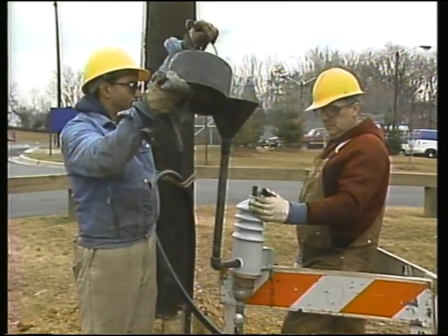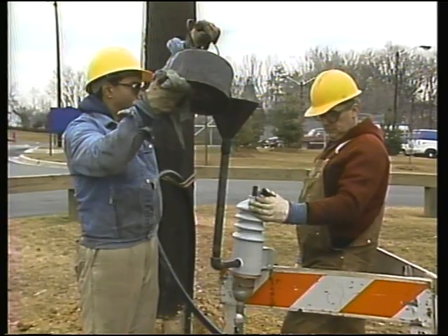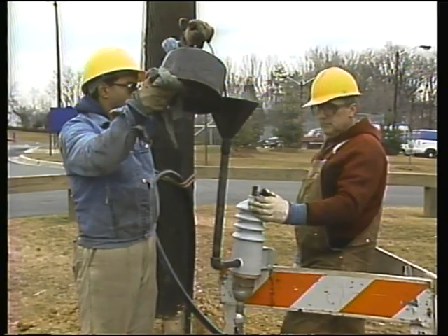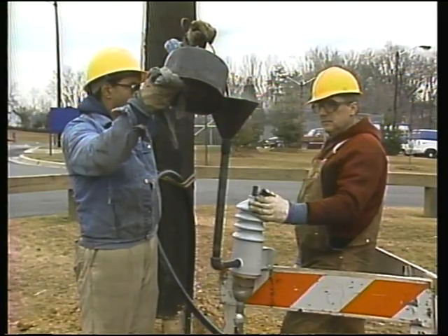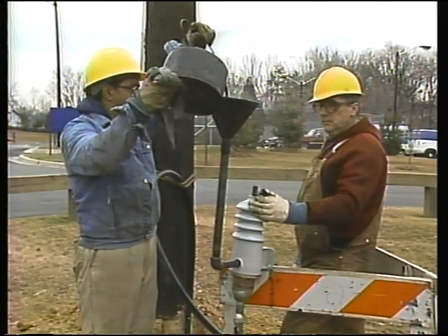The sealing compound serves a number of purposes. First, it provides an enclosure to keep the oil on the paper insulation. The sealing compound also prevents contaminants from getting inside the termination. Before the compound is poured into the termination, the metal housing may have to be heated to ensure that its internal parts are not cold. Cold spots inside the termination could cause the heated compound to cool, leaving voids in the sealant.